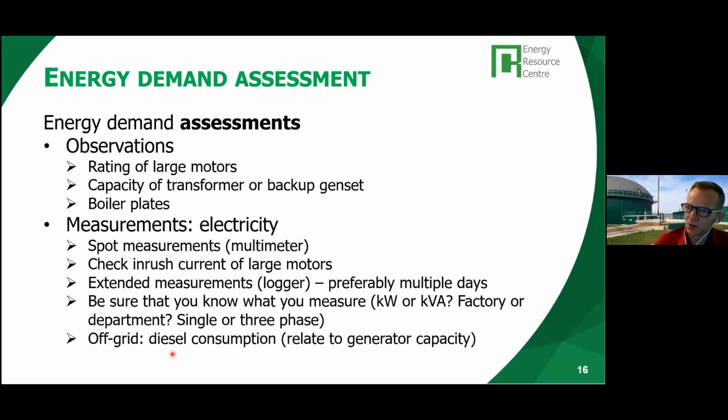And the efficiency in combination with the diesel consumption will give you an indication of the overall production. So it's possible, if you manage to measure the output of the generator, for example, with a power logger, and you can also measure the generator diesel consumption, you can verify the two figures and determine whether the generator is actually performing as can be expected.